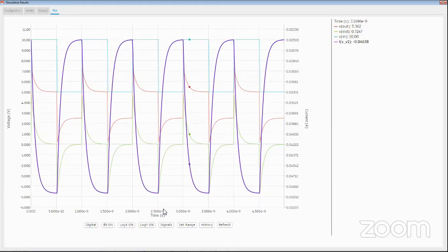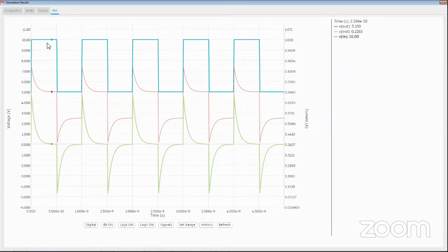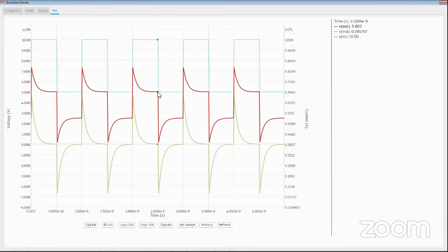Let's clean this up so you guys can see what's going on. I hate that we always display that inductor. You guys already saw the input, but I'm going to leave it for now. We can change it later if we need to. So this one right here is the original square wave, the 5 to 10 volt square wave. And now on the output, we're getting all these peaks going on over here. So the output now, instead of going between 5 and 2.5 volts, is going from like 7.5 to 0.